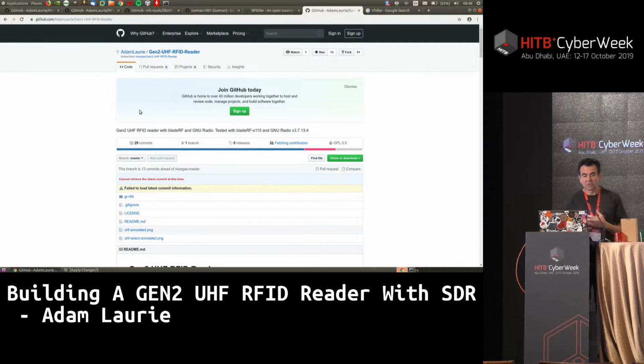If you ground the antenna, and I always get this the wrong way around, in one state it reflects and in the other it doesn't. So the receiving chip can modulate that signal, and it can either choose to send backscatter or not. In exactly the same way that the NFC tag can modulate the coil, an RF tag can modulate its antenna and backscatter or not.